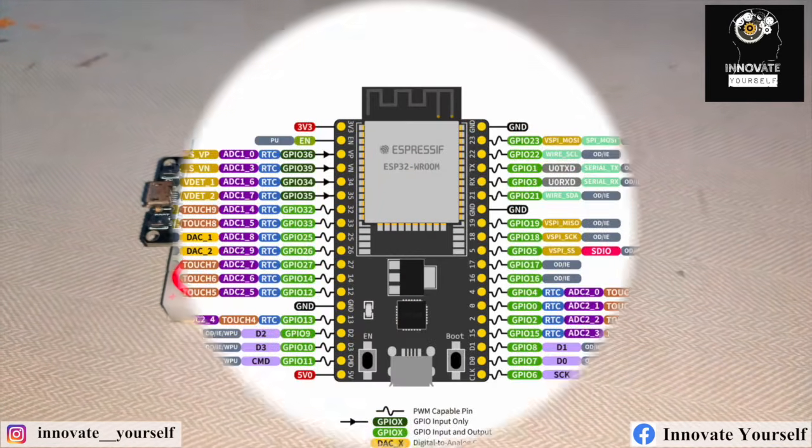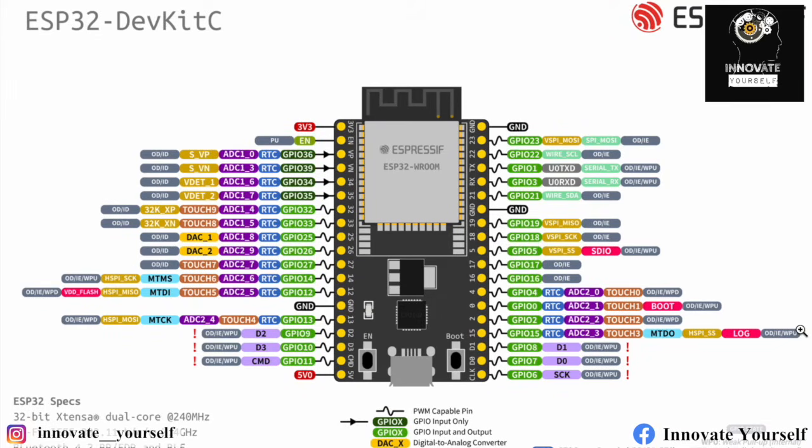Now let's move ahead. Alright, so everyone, you can see here the pinout of your ESP32 microcontroller, which we are going to use in today's session. As in my circuit diagram I have already shown you the connections of your SCK and SDA pins, basically your serial clock and serial data pins, because through those pins only we are going to do this I2C communication between your ESP32 and SSD1306. You can see that the default pins are GPIO 22 and GPIO 21.